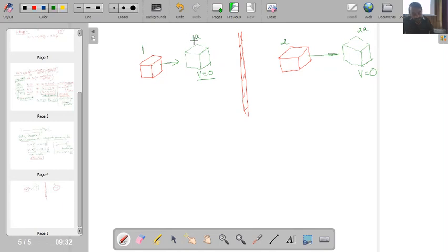Now ultimately my point 1a and point 2a represent the stagnation properties for condition 1 and condition 2. So I can say over here, corresponding to this green fluid element, I will have temperature T naught 1 and pressure P naught 1, the stagnation pressure corresponding to this situation. And here I will have temperature T naught 2 and pressure P naught 2. Is it clear?